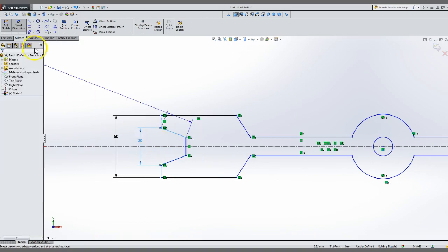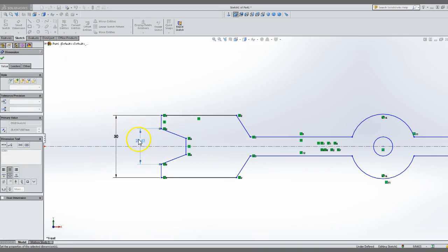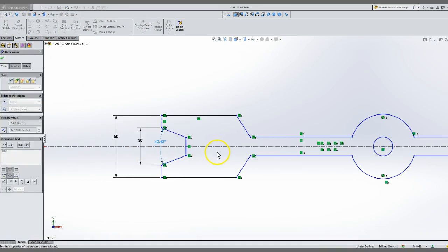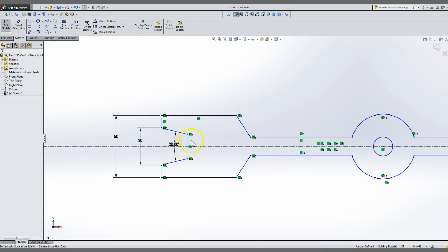So just so you can see that one more time to see what numbers I used to get that. I clicked one angled line, then the other angled line, and now you can see I can pop in and force that angled dimension. And if you need to move these around so that they don't get in your way and drive you crazy, that's fine.